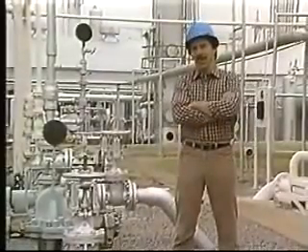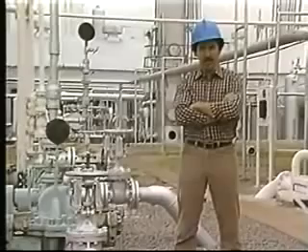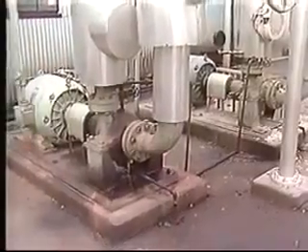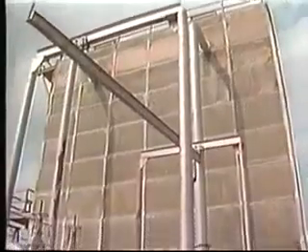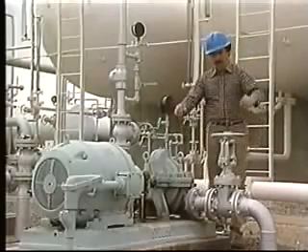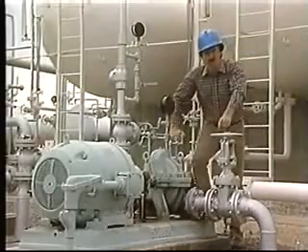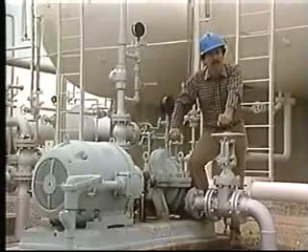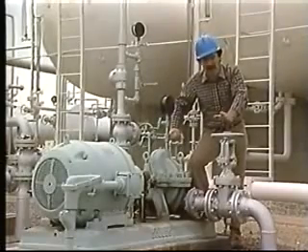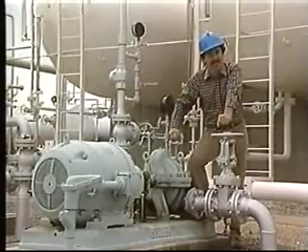So, when are centrifugal pumps used? Usually when you have to move a lot of fluid, like emptying storage tanks, moving processed fluids in gas plants, providing emergency fire water, circulating cooling tower water, and, well, many other applications. What we're saying is that you'll see and work with centrifugal pumps just about every day. So you need to understand them, and this module will help you do just that.